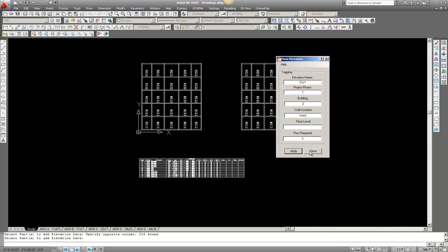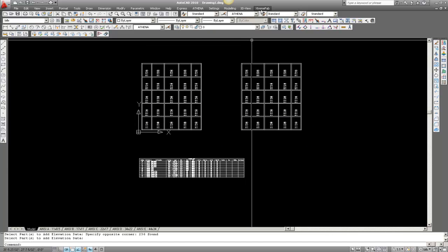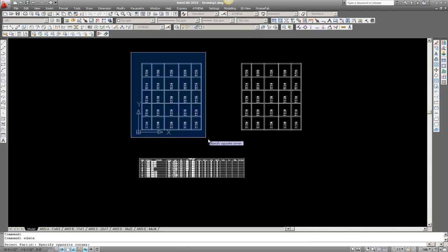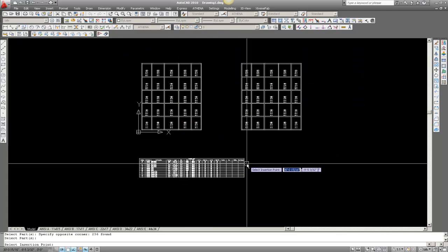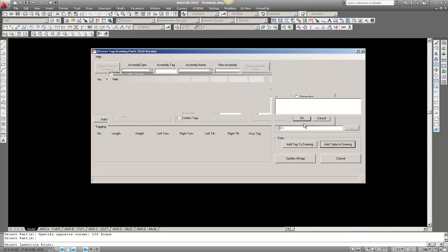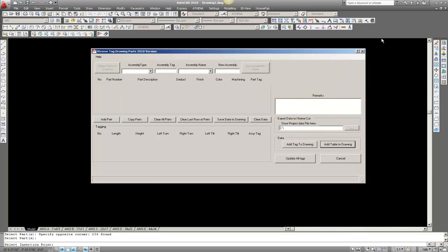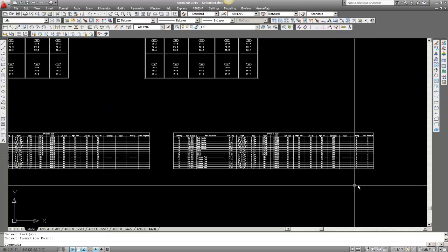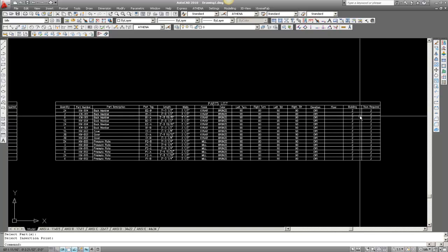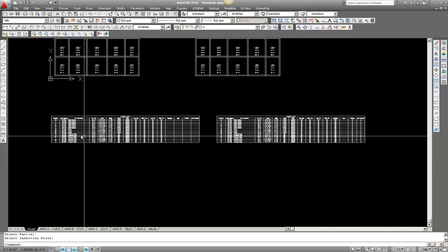And once I do, when I put out a table, once again I'll put that over here. I can do a part description, list with quantities, click OK. It'll actually put that part list out with that information from that elevation, where it's located, and the whole works. Okay, and how much is required, and you'll notice it multiplied the list.